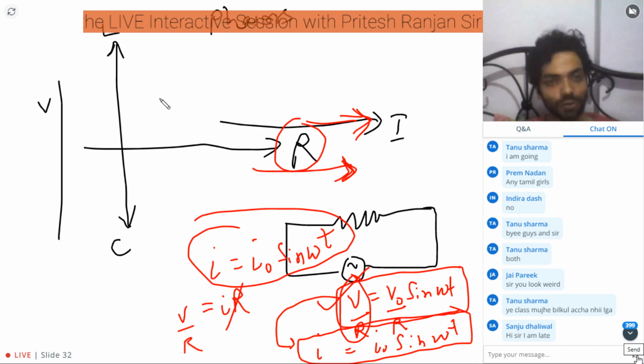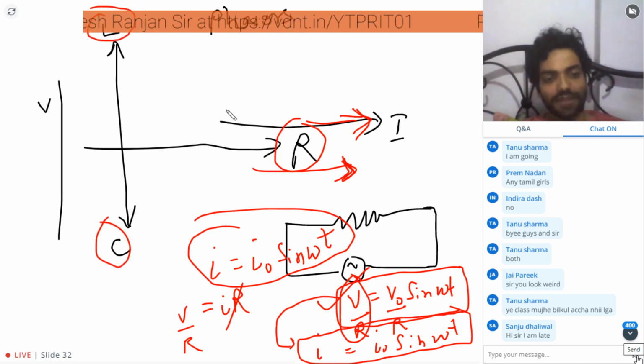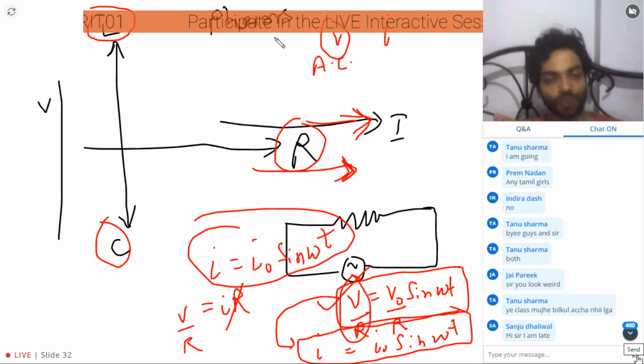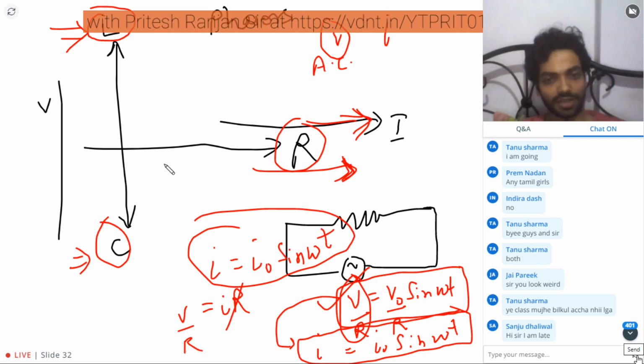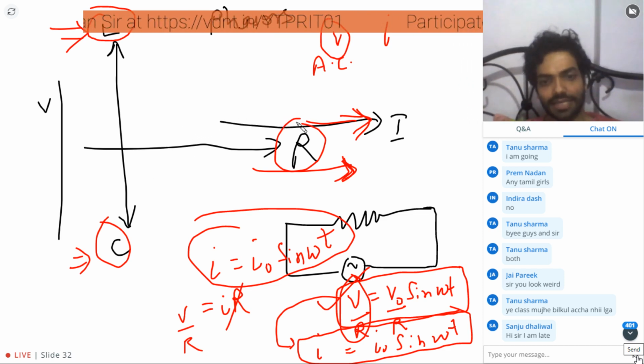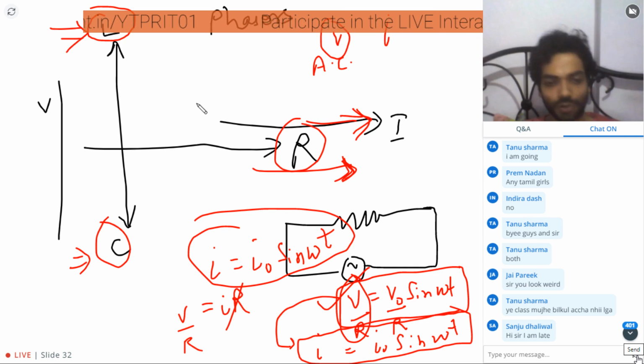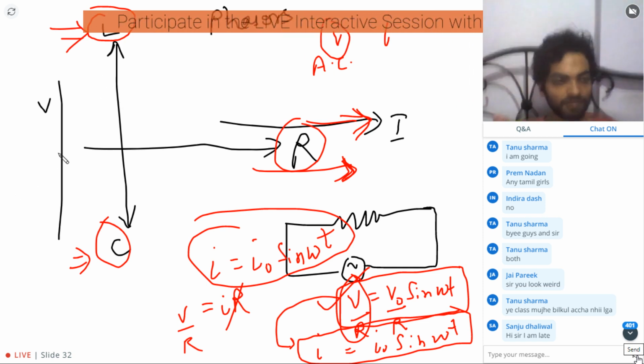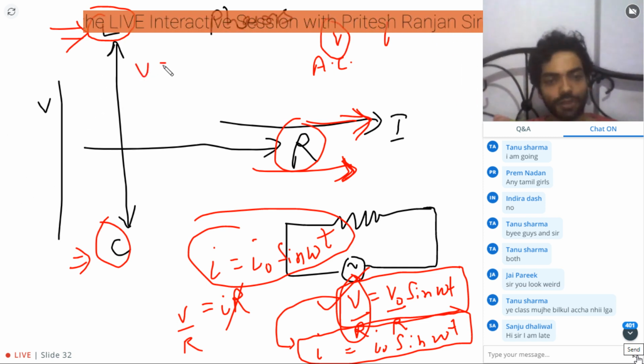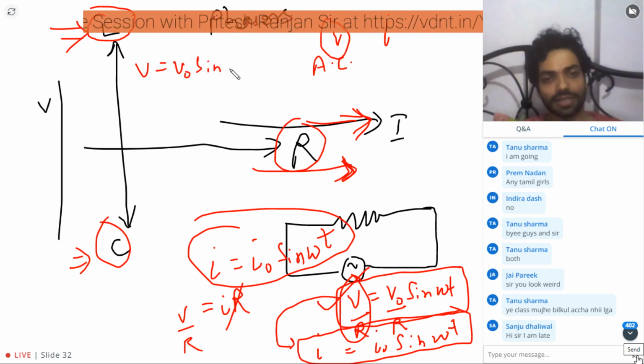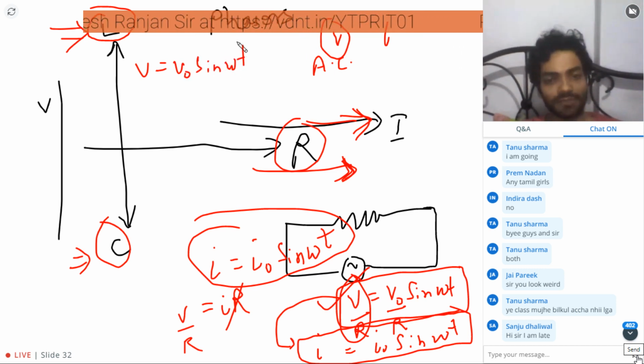So let me now use phasors to determine the value of current when the value of voltage is given by an AC source. The main thing concerned is to get the value of current or voltage through the L or C circuit components. As you can observe here, I is towards the right. So I'll take the value of voltage as V naught sine omega t. Let us fix this value of voltage for an AC circuit.